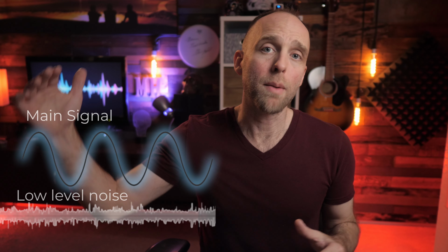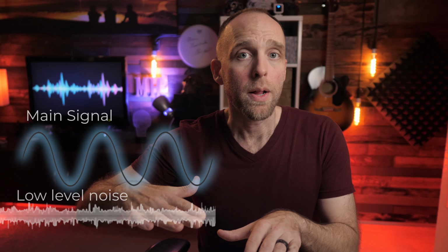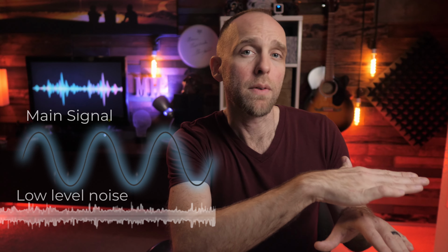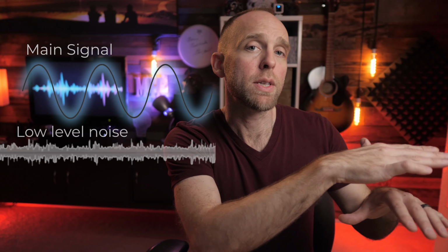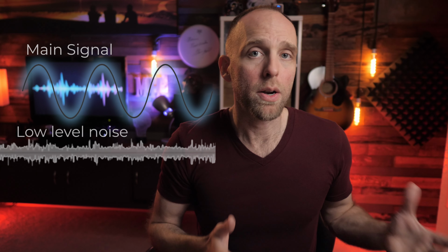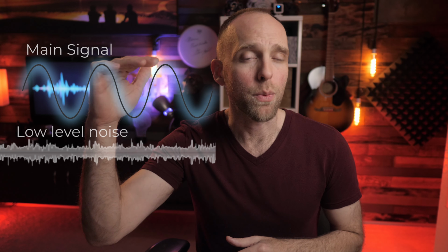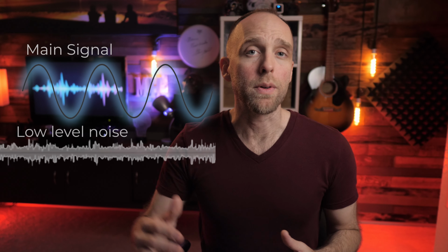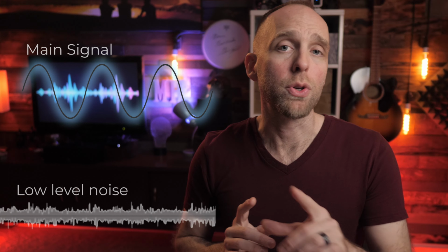And if we reduced our main audio signal at the beginning of the chain and put it closer to the noise floor, then we boost that overall signal with the next device, we have the potential of adding more noise to the overall signal. And that overall noise floor starts to get louder and more audible as things like hiss or hum in our audio signal. So we always want to have our main audio signal as loud as we can get it without clipping out any of the equipment in our chain. And this keeps our main audio signal as far above that noise floor as possible. And that is signal to noise ratio.